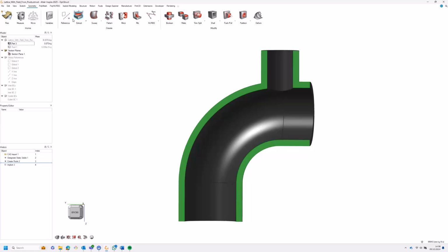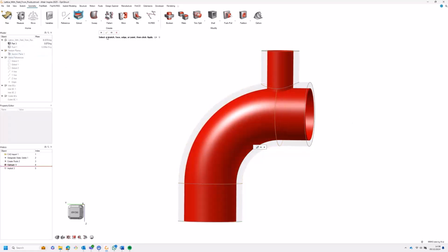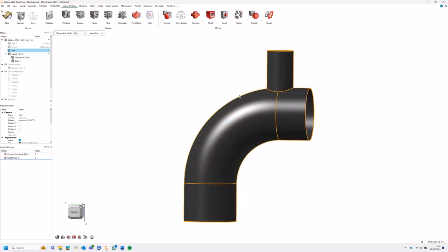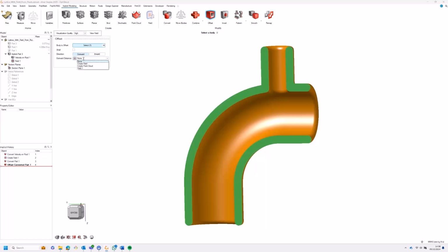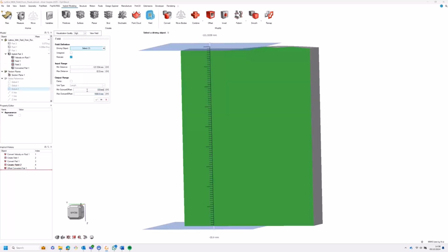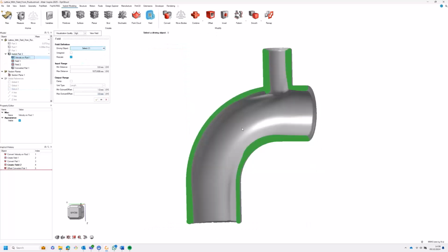A useful workflow is to create a pipe geometry where the thickness of the pipe is driven by the fluid pressure. Use the Extract tool to create a new part with the surfaces to thicken into a pipe. Use the implicit offset to start thickening the extracted surfaces. Apply a field to the outward distance, and we can try to use the previously converted velocity results, but it isn't the results type that we want to use.